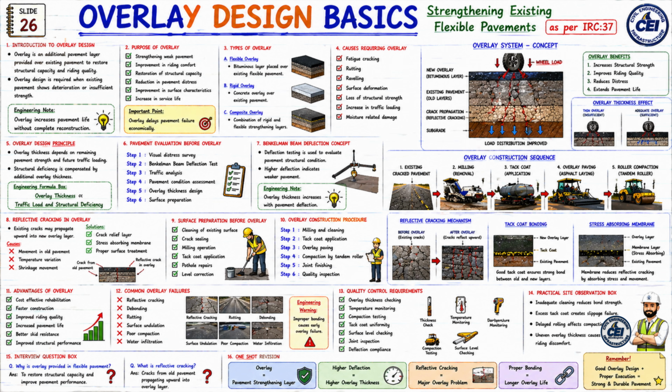Look at the overlay construction sequence below. Step 1. Existing cracked pavement. Step 2. Milling operation. Step 3. Tack coat application. Step 4. Overlay paving. Step 5. Roller compaction. And this is the practical overlay construction flow.